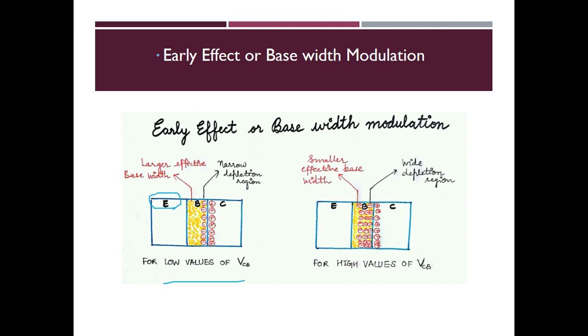Depending upon the doping concentration, the emitter is very high, the base has very, very low doping, and the collector is moderate, between the emitter and the base. We already know that the depletion width penetrates deeper whenever the doping concentration is less.